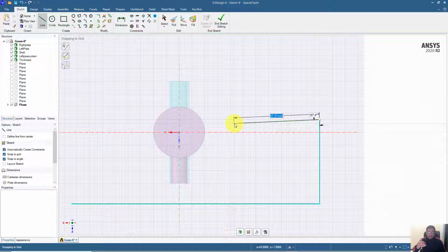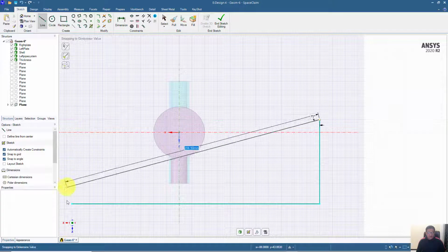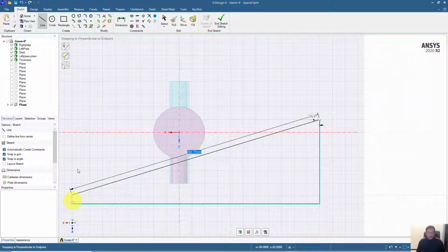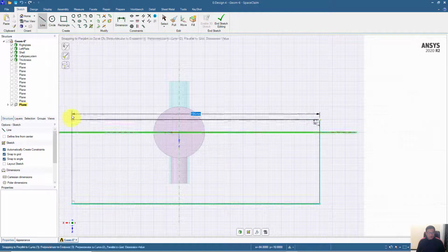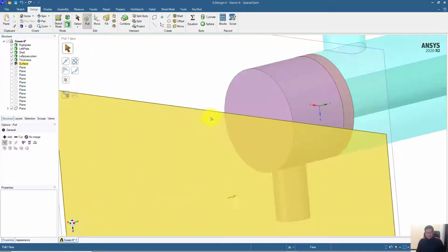This is the initial spacing we apply for the initial design of the baffles in the shell and tube heat exchanger. Then make the straight line, and it should be on the same line, but it can be of any shape, so it does not matter here. The line over here should be a straight line, so you can make this line an inclined line. This will not make any difference in our overall geometry for the baffles. And simply click on end sketch.